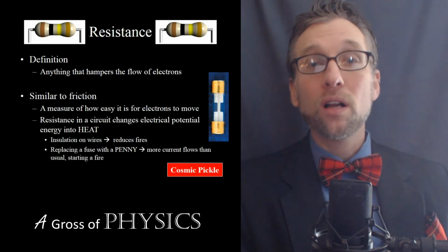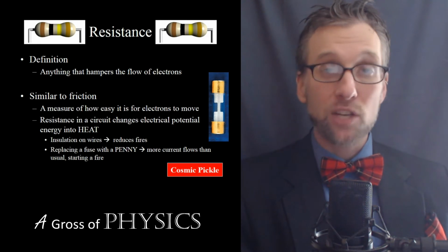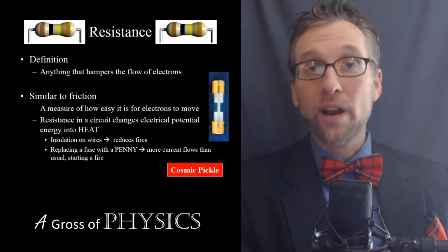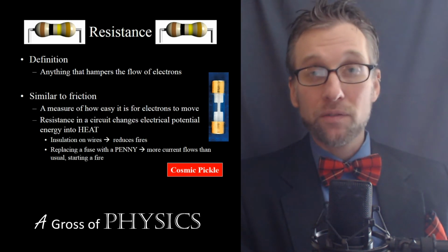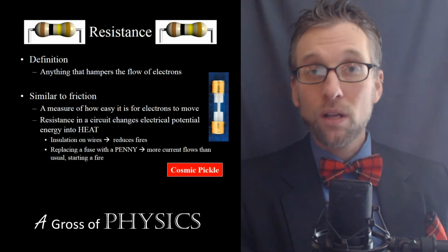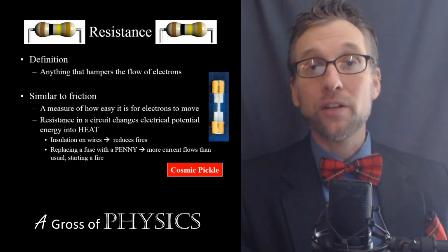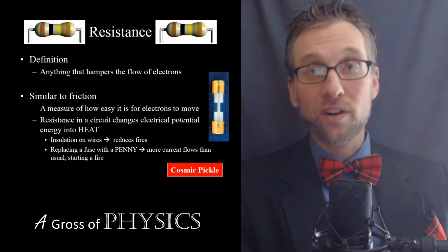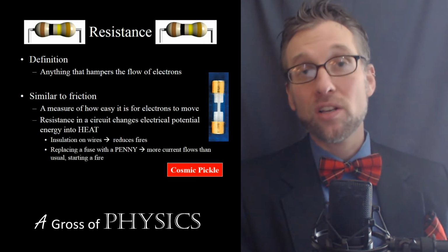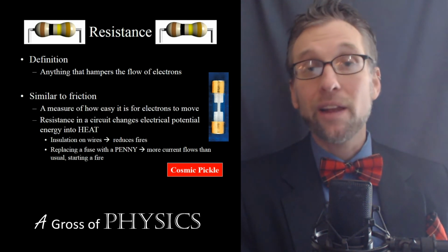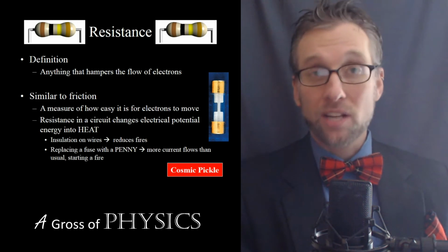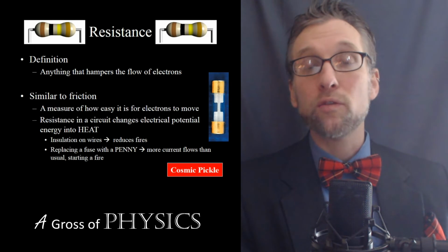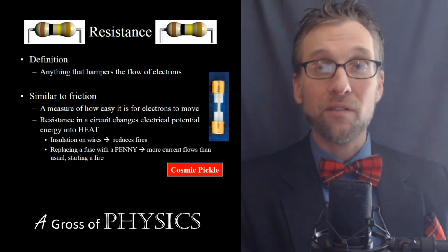If you use the wrong diameter wire, a different gauge wire than you should, you can produce a situation where an expected amount of electricity will flow, but the wire can't handle that much amperage. So what happens is you have overheating of that wire, and it could cause the insulation itself to melt, and ultimately the walls could catch on fire and you can burn your house down. So it's important to use the right gauge wire for the right circuit that you have.